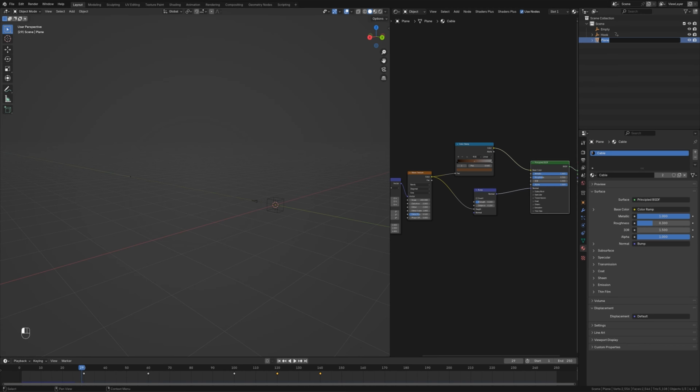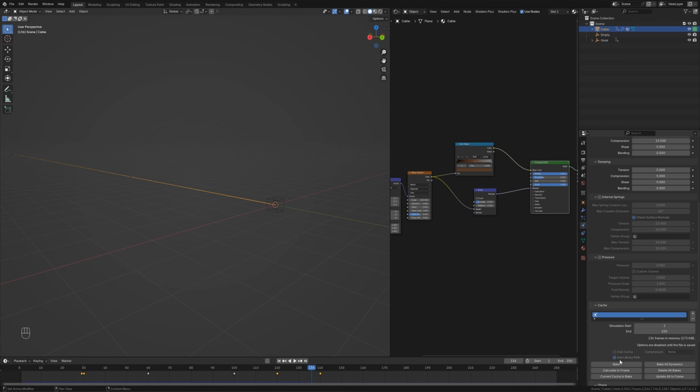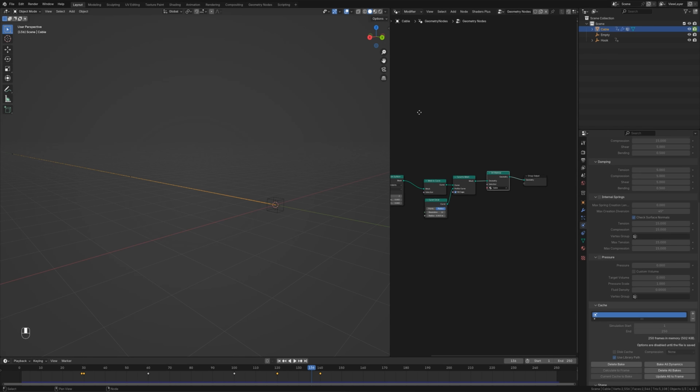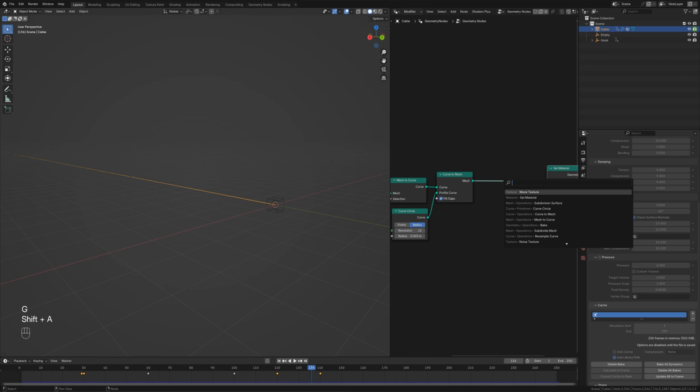Disable the cable in render until the launch frame and then keyframe it back on. Then you don't see the initial pull and the rope appears to be launched from the grapple gun. And also, every time when working with simulations, bake the simulation before rendering, and you can even bake the geometry node setup to make sure it's stable in the final render. This requires you to save your project file, which you will probably do anyway.